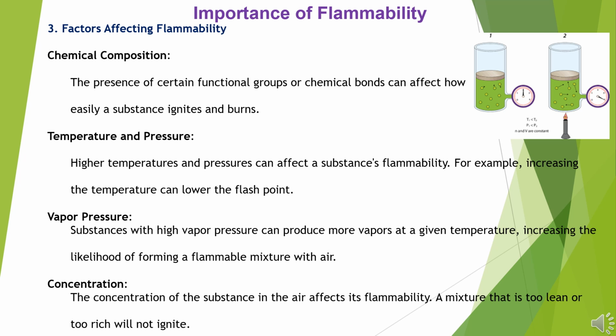Vapor pressure. Substances with high vapor pressure can produce more vapors at a given temperature, increasing the likelihood of forming a flammable mixture with air. Concentration. The concentration of the substance in the air affects its flammability. A mixture that is too lean or too rich will not ignite.